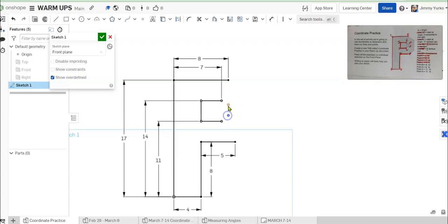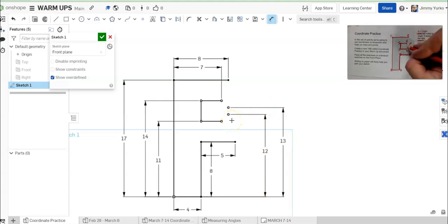Now we just need to align them vertically, which we have yet to use a vertical constraint of 12 and 13, so we'll need to put a dimension on from the origin to the first one, which was 12, and from the origin to the second one. Second point is 13. Now that defines M and N. It's done. So we can connect those dots.